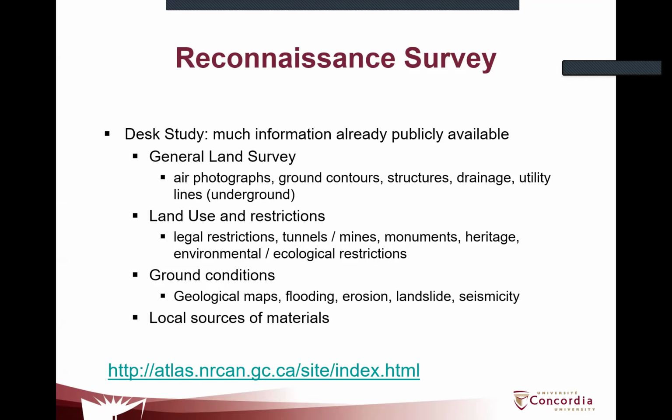So the ground conditions are also important. So we look into the geological maps, the flooding. The flooding is quite important because you want the elevation of your highway to prevent flooding from getting into the pavement structure. But also, if you are in a mountain area, you might want to pay attention to areas susceptible to landslides, and earthquakes will also affect this because the type of terrain, when there's an earthquake, might trigger landslides. So they go hand in hand.